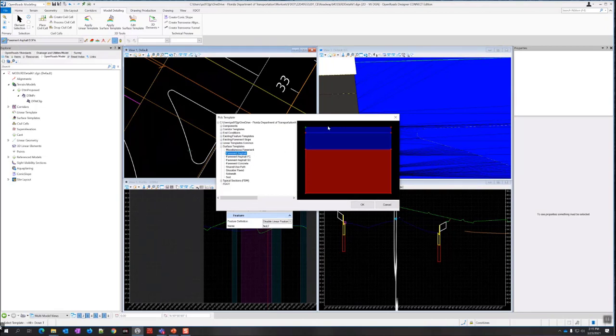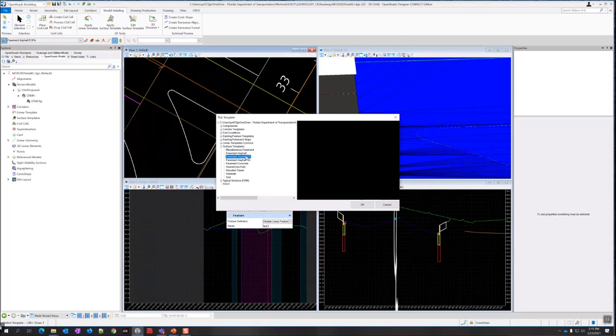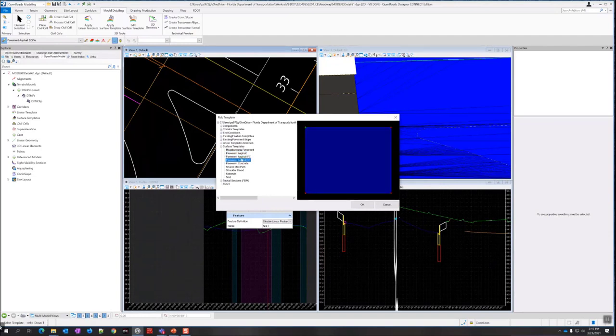The new one, by the way, on the Pavement Asphalt, this is something new with ORD. Since we started in quantities, since we're quantifying the pavement through this, we need the pavement design reflected. So the friction course and the structural course have to be separate components, and they're separate feature definitions. In fact, that's why we have these friction course and structural course, if you need to build your own. This one is set up that way.